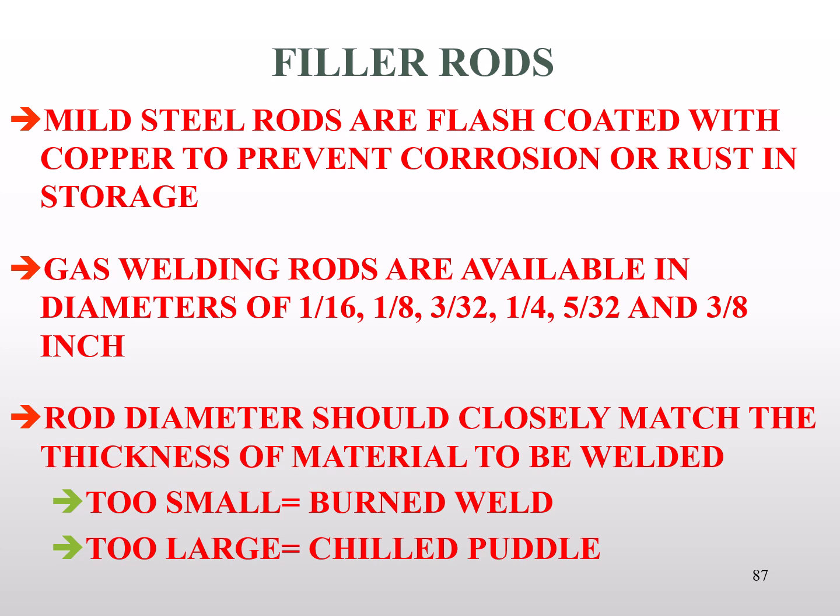It's very difficult to keep a puddle flowing if we go with too big of a rod. So what do we need in this case? The Goldilocks filler rod, the one that matches the material. It'll flow, it won't burn up, and you'll make a good, healthy weld.